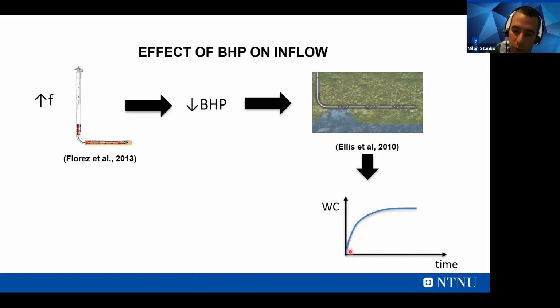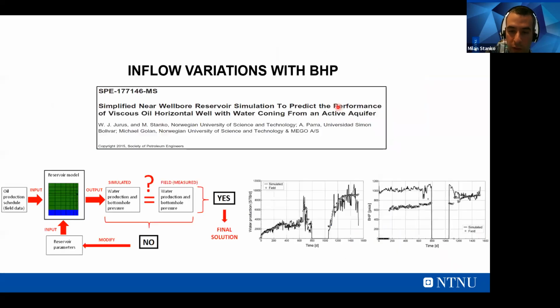So people were concerned that if you had already a behavior of expected water cut versus time, by doing that you're going to accelerate and create early coning and produce early water breakthrough. So we were looking at this issue, not completely successfully, using a reservoir model and history matching our model to the production data, and then trying to predict from there also the bottom hole pressure.